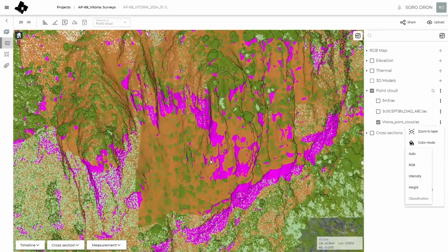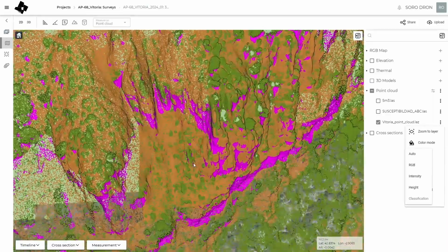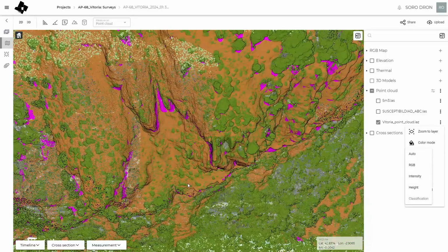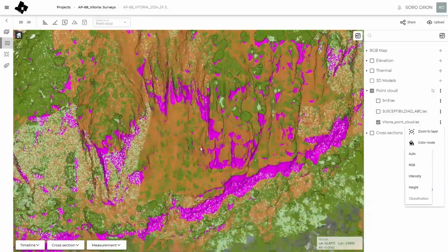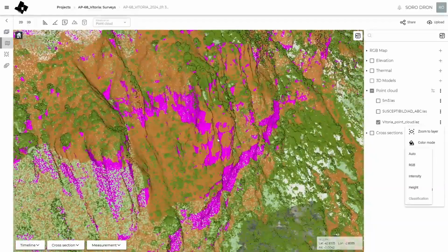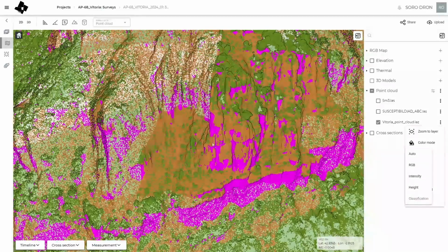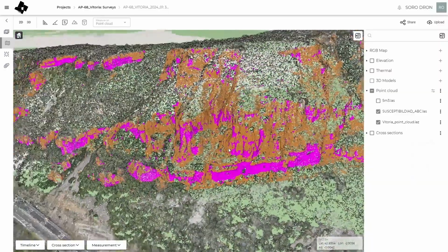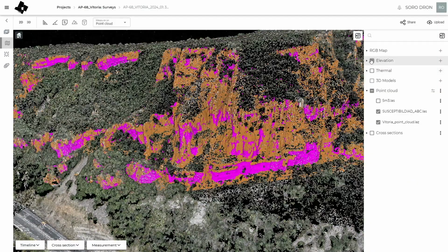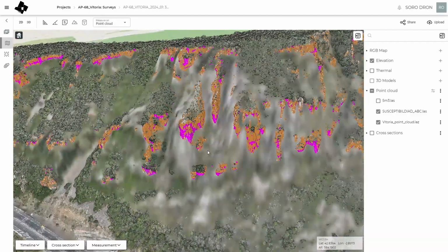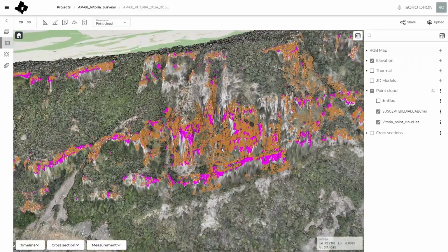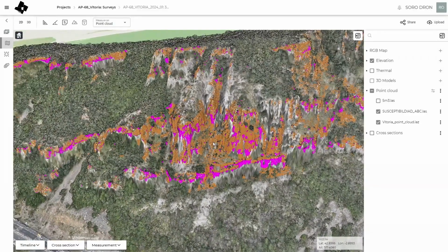Overhang means that these points will never be correctly described using a digital elevation model, because in the same planimetric point you cannot represent two different heights. So you need to use a full 3D environment like point clouds. We can use these beautiful point clouds, for example, to assess the parts of the scarp that are susceptible to produce rockfalls. This is the more steepened part of the cliff, the overhangs and the non-overhang areas.